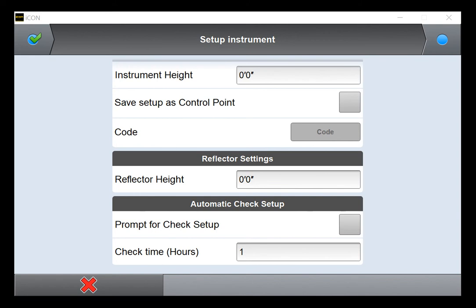If you ever receive a message saying that your measurement is not possible because the total station is out of level, you must fix your level and complete another setup anywhere by measuring your reference control points. Never adjust your level and go straight back to laying out points. Do not just ignore the error saying that measurement is not possible because the total station is out of level.